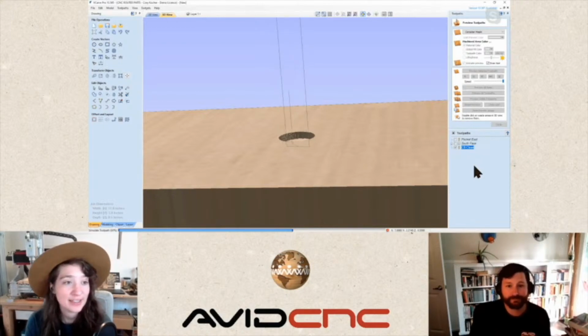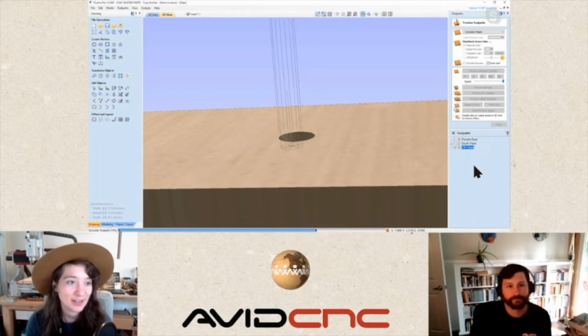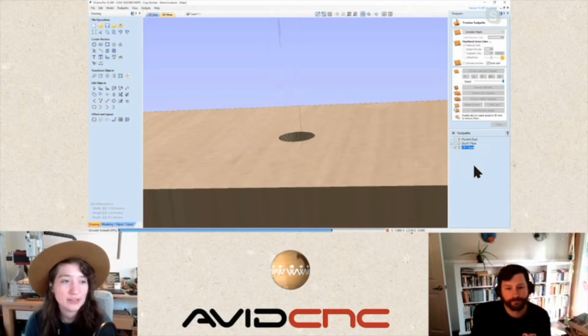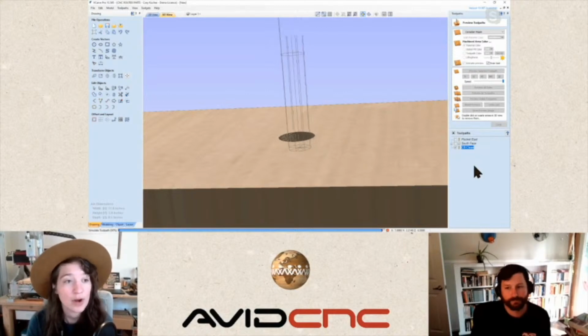Yeah, you have to consider the limitations that your machine imposes versus also the limitations the vectors impose, and also the simulation versus actual. So I do encourage you to also record your times, and then check your time predictions in your toolpath to see how accurate that is, and you can change the scale ratio, and it will give you more accurate prediction times in the future. Yeah.